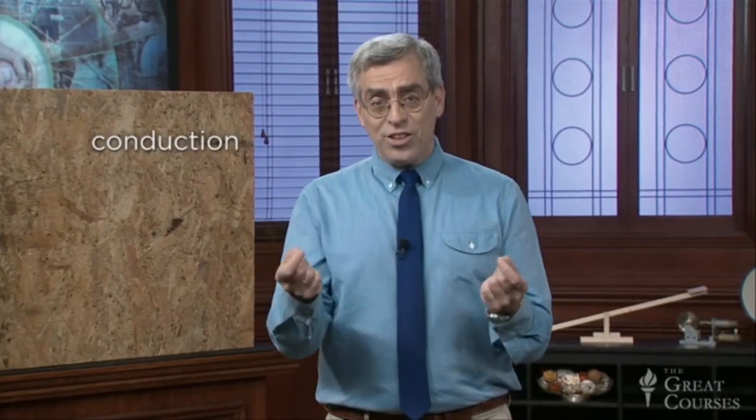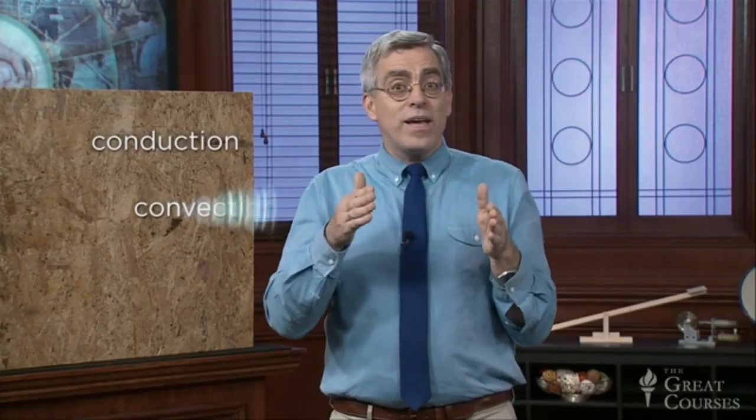No matter how well insulated your building envelope might be, its energy efficiency can be totally compromised by air infiltration, which can cause heat losses of up to 40%. Recall that the principal purpose of insulation is to resist heat transfer by conduction, but heat can also move by convection. And many installations, including all types of batting and loose fill, do little to prevent convection.